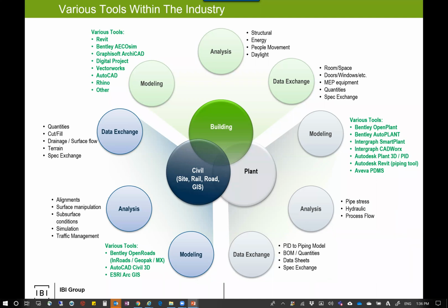But in the world of BIM, I've got building-based BIM authoring tools, civil-based, and plant-based. Building tools are all governed by the IFC standard. Now, I think in your standards course, Megan's going to talk about that a lot, I hope. Today at George Brown, I asked, has anybody heard of IFC? They all put their hand up. And I said, not Issued for Construction. Industry Foundation Classes. All those hands went back down. I like describing IFC as kind of like the PDF for BIM. It's an open format governed by an ISO standard, and it governs the taxonomy of the data within a building model.